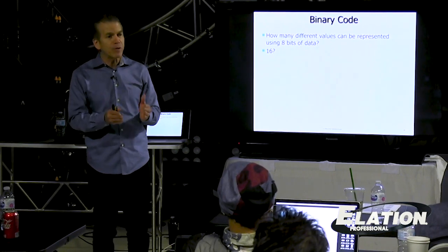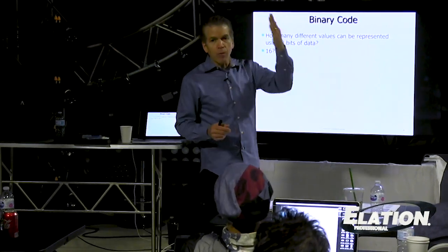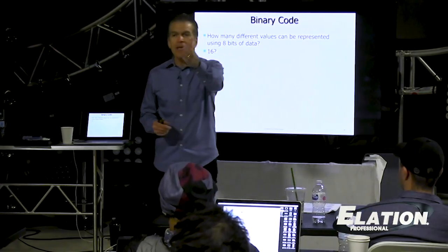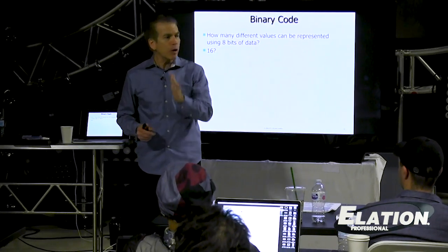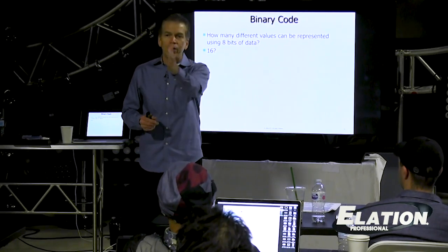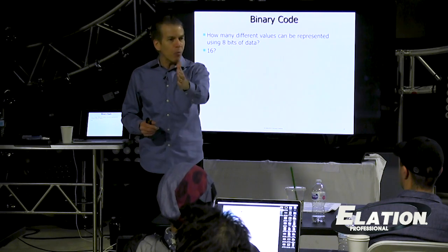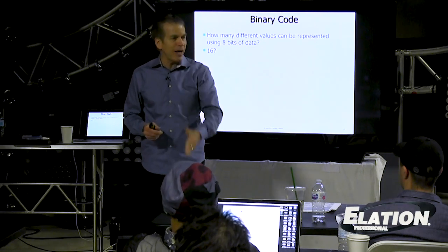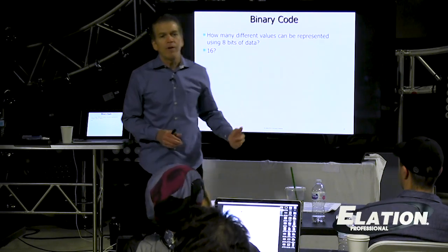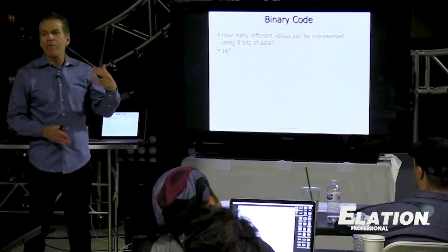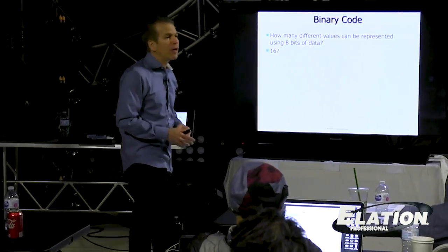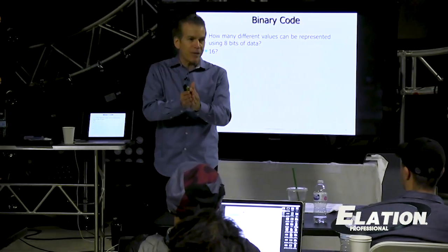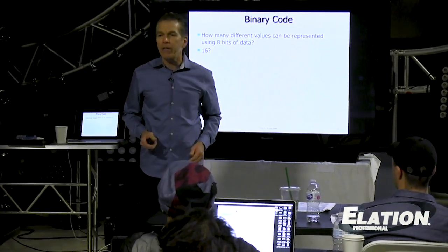It's much more accurate. So if you're trying to throw 40 feet to downstage center with 256 steps of control, you might be able to target to the left or to the right of downstage center, but not exactly downstage center. But with 2 bytes, or with high resolution 16-bit control, now you have amazing accuracy and you can dial it in exactly where you need to go.